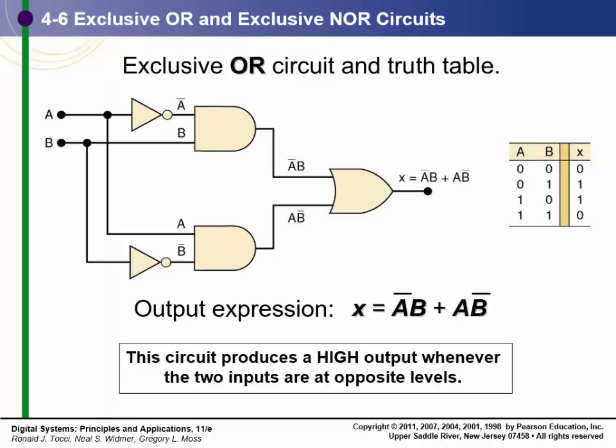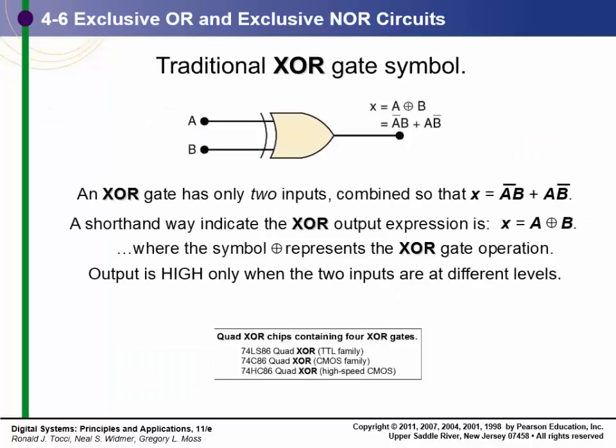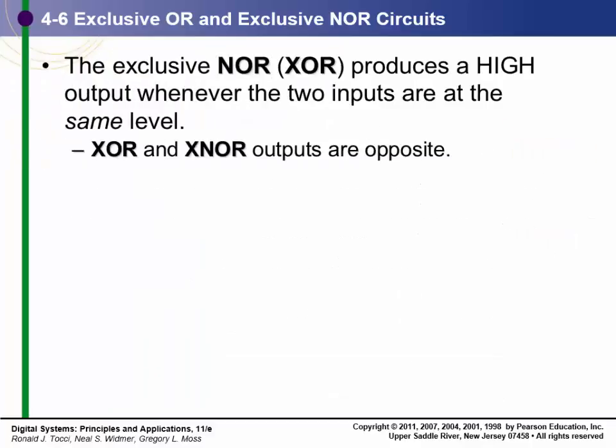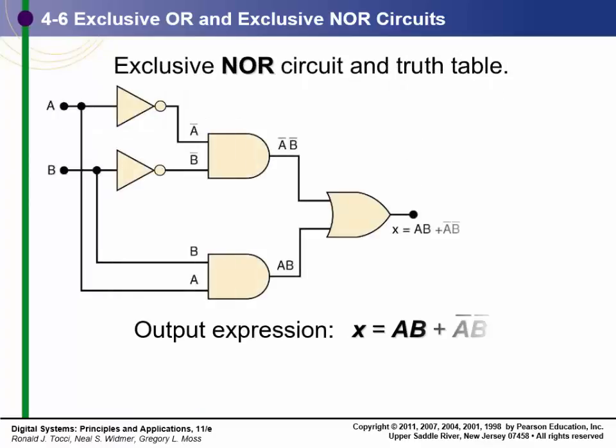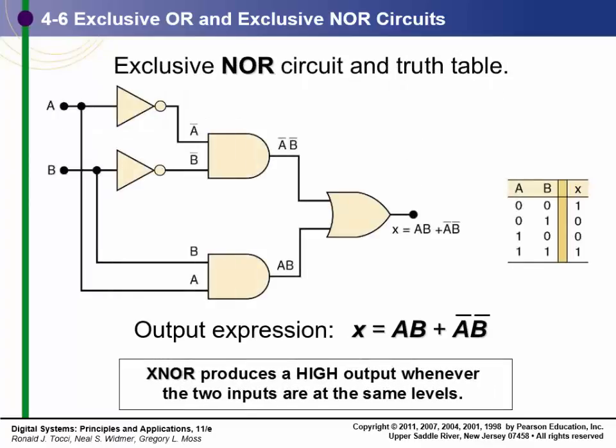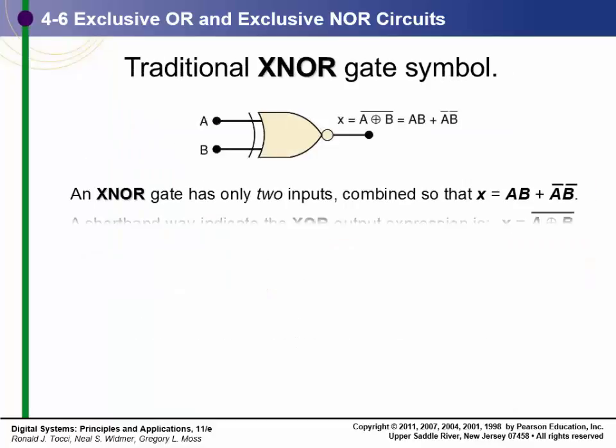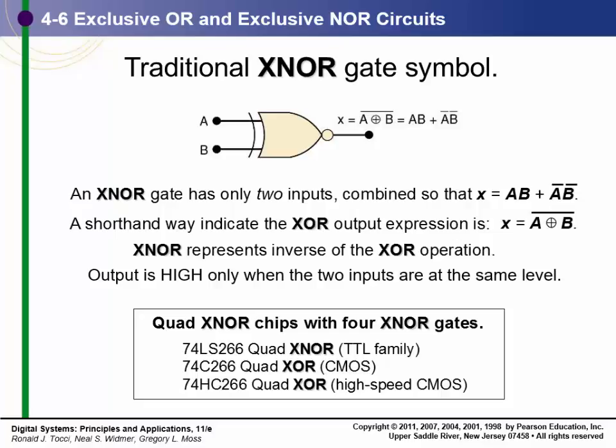Right there. The exclusive OR I kind of flew over. I'm not going to worry too much about the exclusive OR. You do need to know what it is. I talked about it before. There's also the exclusive NOR right there, which is the opposite. Those are used a lot in comparators and parity checkers right there. And they're also used in adders in some cases right there.